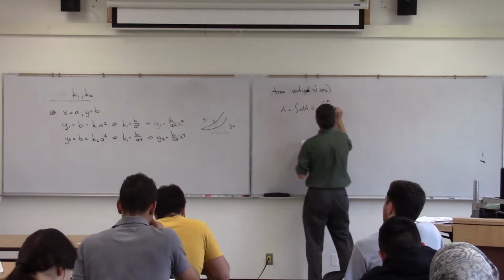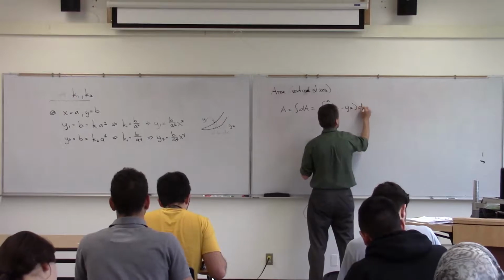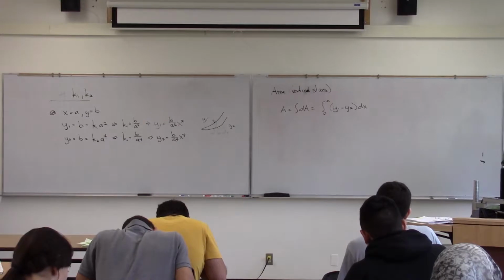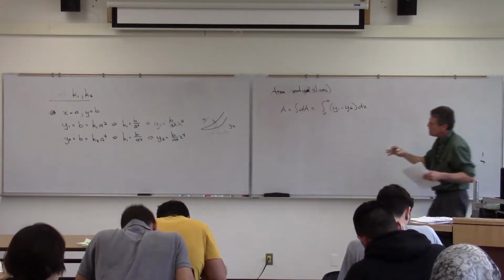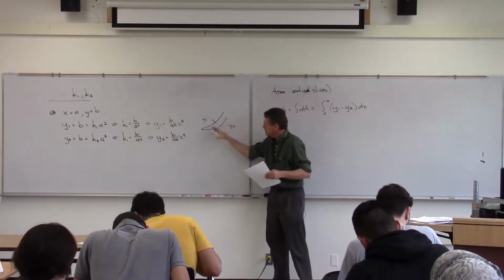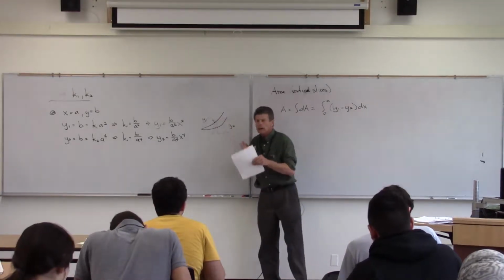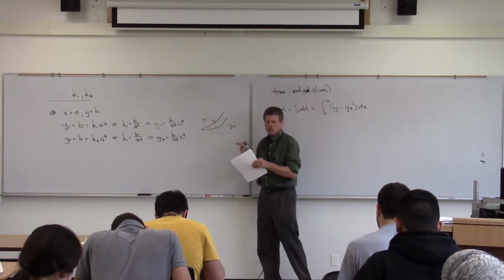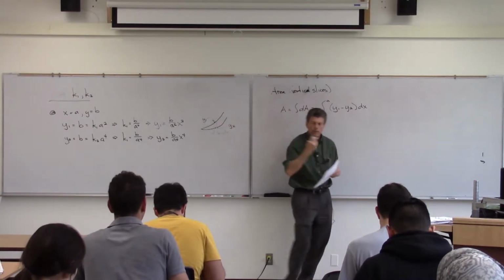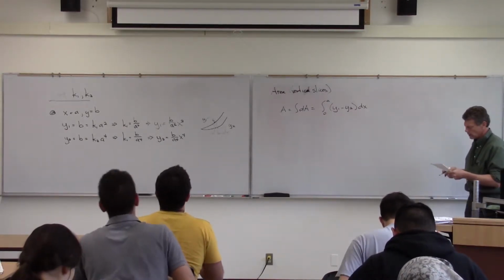And what we want to do is then think of our rectangle. But our rectangle is now going to be a little bit different. It's not just the y. It's going to be y1 minus y2. So again, that bottom portion is going to be coming up too. But that simply defines a rectangle. When we go to an infinitesimal size there, the curves at the ends don't matter. And we'll be dealing with a rectangle that will be changing in size and moving along up there too. And moving along up there is going to be important because our first moment of areas are going to be looking at those moment arms as we go along.